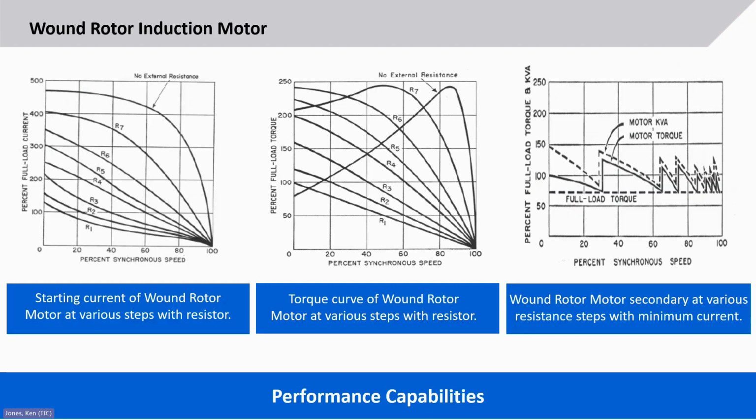So oftentimes we get asked if we can just apply a wound rotor machine. And since we know that it's a design D starting condition, we can look at it and say that the resistor at any given point, because you can have series resistors in place during starting, that you can have many different starting conditions associated with it, by simply bringing resistors in or out of the motor start condition.